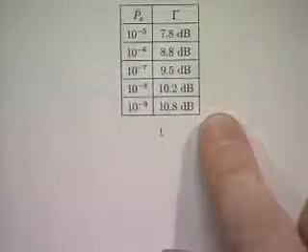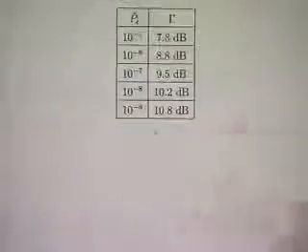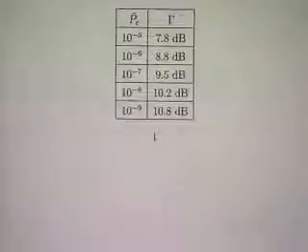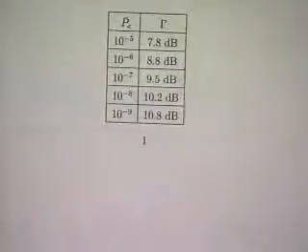If we know the gap for a given type of modulation, and here it is for PAM and QAM, we can almost immediately compute the data rate that we would transmit over the system. Very simple formula. You know the signal-to-noise ratio. You'll know the gap. You may memorize them for a few different commonly used probability of errors. You as an engineer pretty much know how fast you can go on this transmission system.